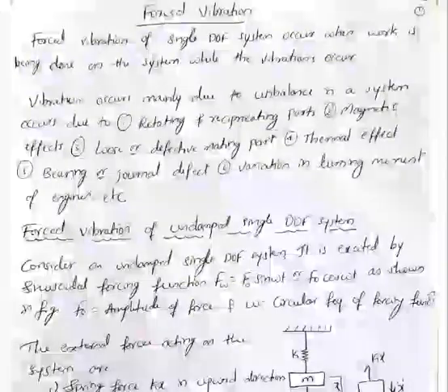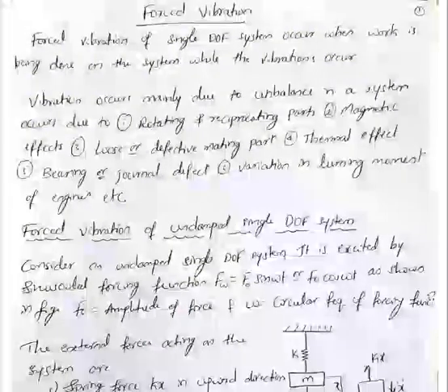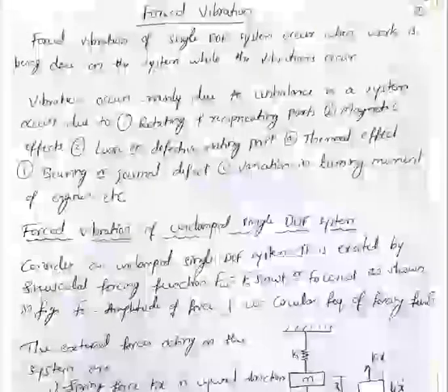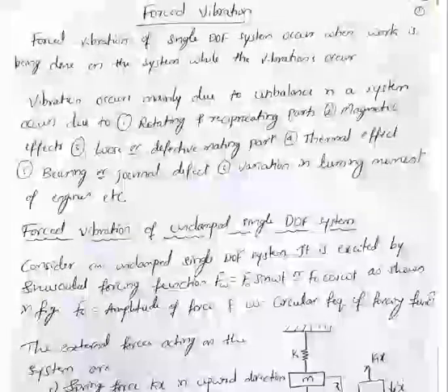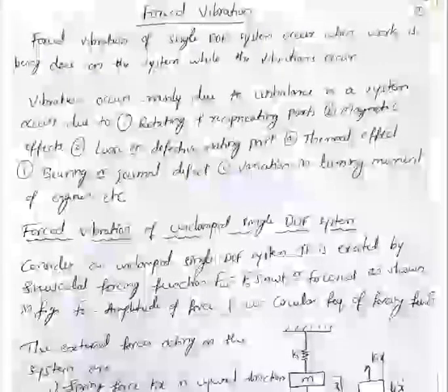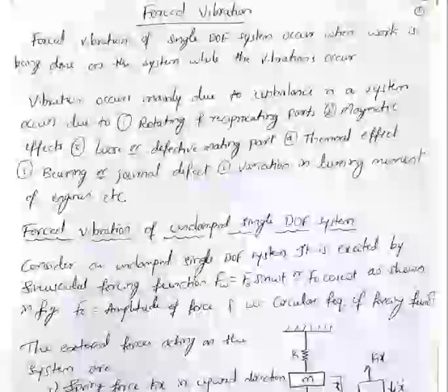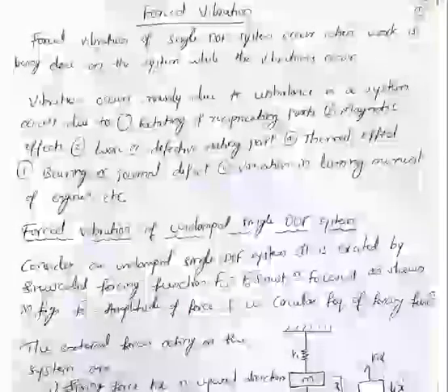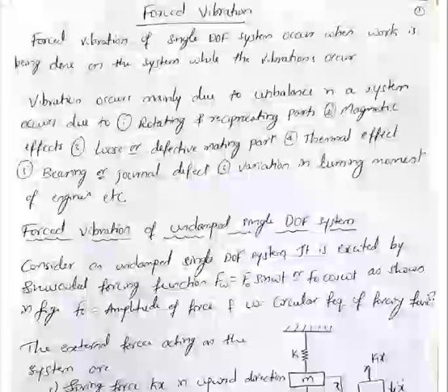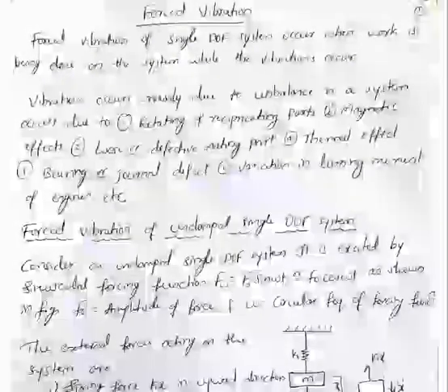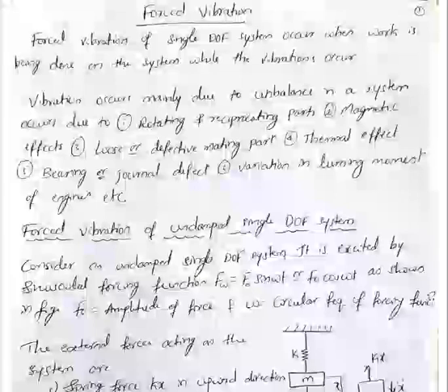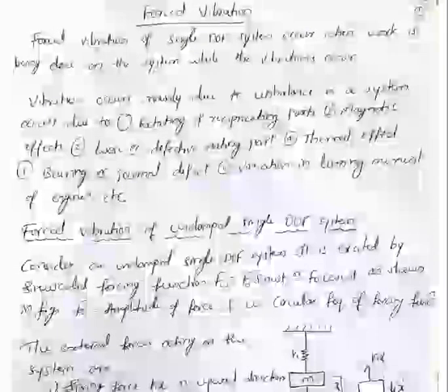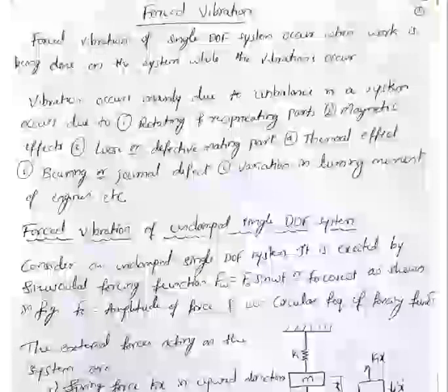The response of a system to harmonic excitation is called harmonic response. Similarly, the response of a system to a suddenly applied non-periodic excitation is called transient response. The sources of these responses may be anything, but the most typical examples of random forcing functions are earthquake excitations and acoustic excitations. They all come under the random forcing functions.